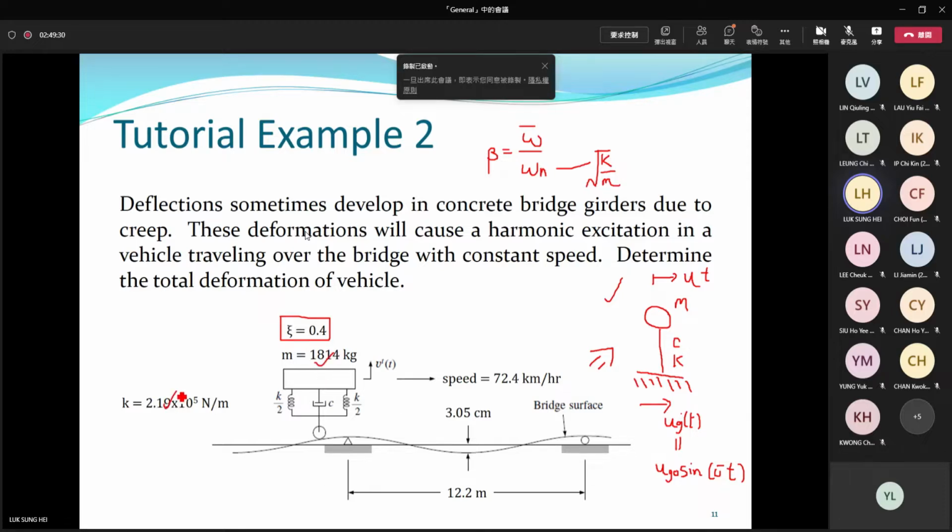So you can evaluate natural frequency directly without difficulty. The difficult thing is the loading, because here we transform the problem to a ground movement. So you have to find the corresponding expression for our ground movement function.